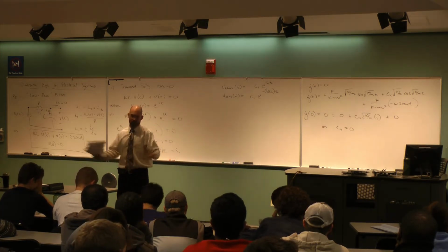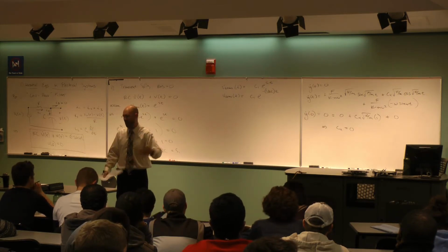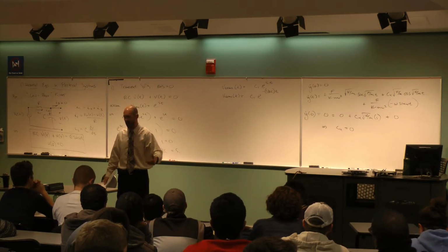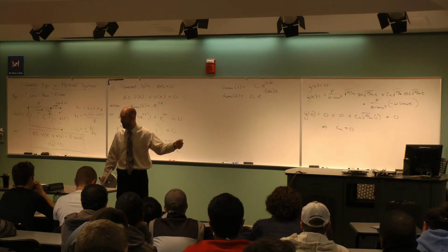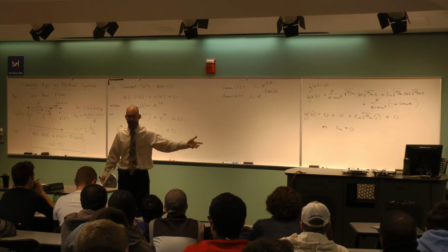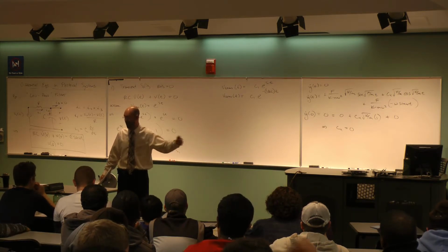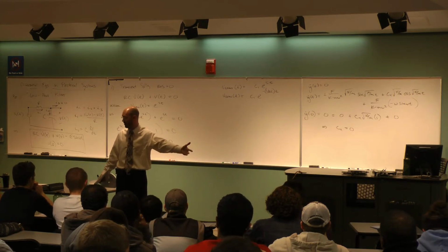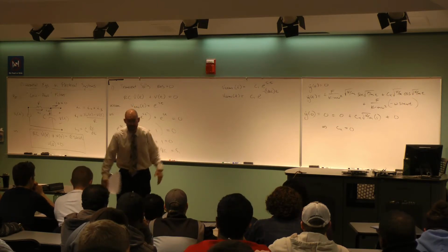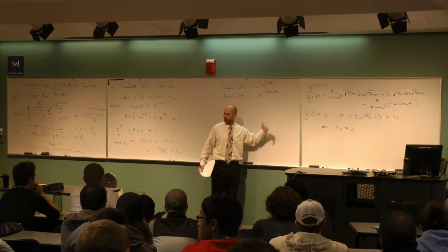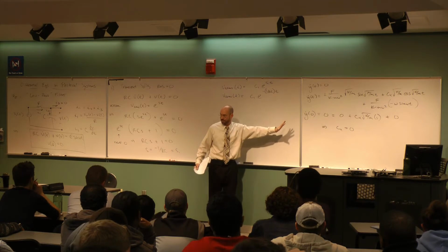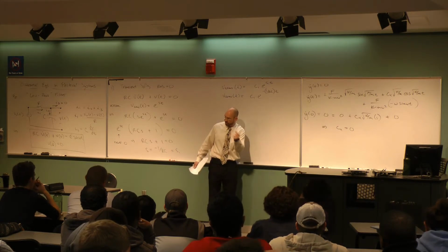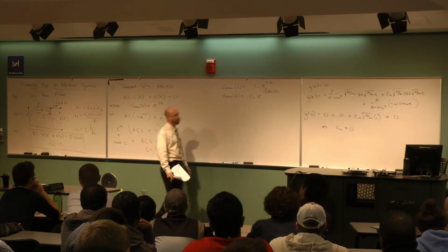Think about the numbers, right? Typical numbers in your lab. I got a resistor, which is whatever, a couple of ohms. I got a capacitor, which is what? Microfarads. E to the minus 6 times a couple of ohms is still e to the minus 6. If it's times 3 or 400 ohms, it's e to the minus 3. These things decay in electric circuits on the order of milliseconds, right? Very quickly, the transient stuff's gone. Okay, but it's part of the answer because initially it affects the total solution.